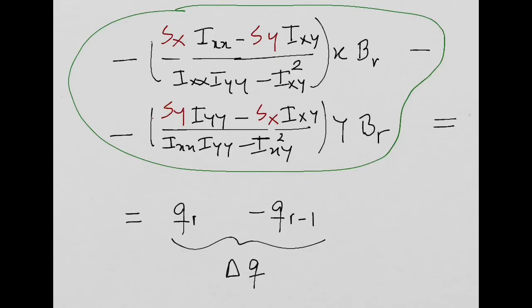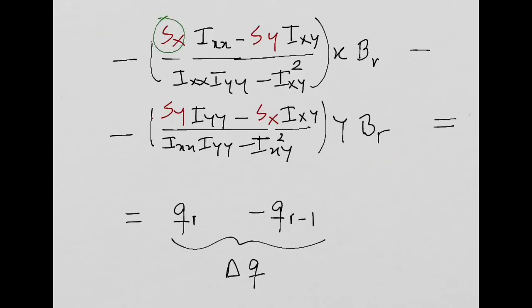So when I cross the boom, the variation on the shear flow is given by this, what I have here on the left-hand side. And we know everything we have on the left-hand side. Because what you have on the left-hand side is the transverse shear forces, Sx, Sy. We know that.